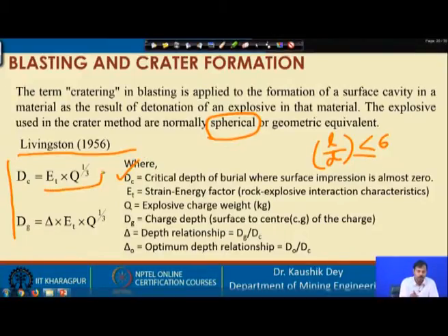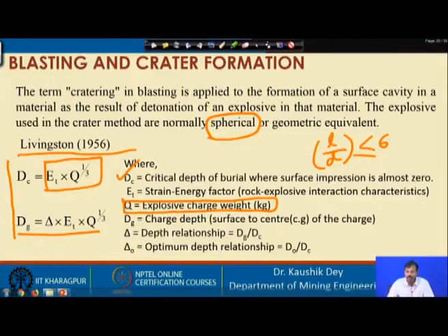as this equation, where Et is the strain energy factor, that is the rock explosive interaction characteristic, and Q is the explosive charge quantity expressed in kg. And the depth of charge can be related to the crater volume, and that can be obtained using this equation, where dg is the charge depth, surface to the center of the charge.